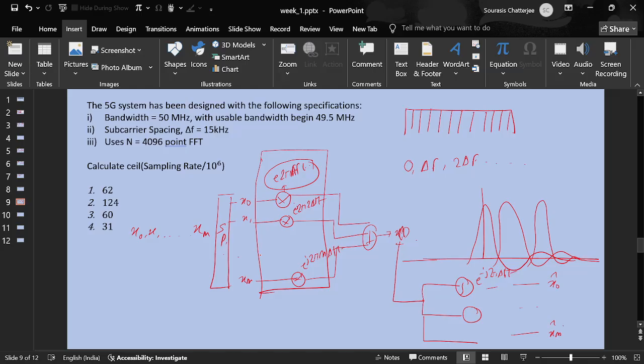So multiple paths, each path arrives at different times. When you have a second path which is arriving with too much delay, it interferes with the previous path. So they both combine non-coherently, and your data in each subcarrier is corrupted. True. So basically, you are saying that to protect against inter-symbol interference, you are introducing this CP, right?